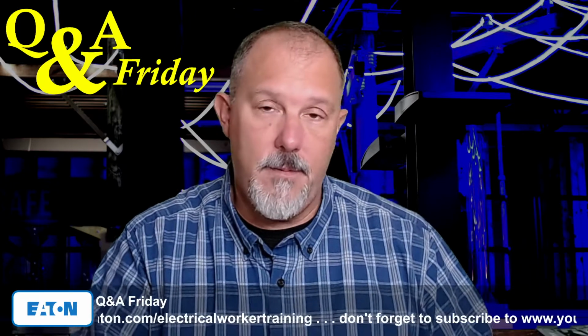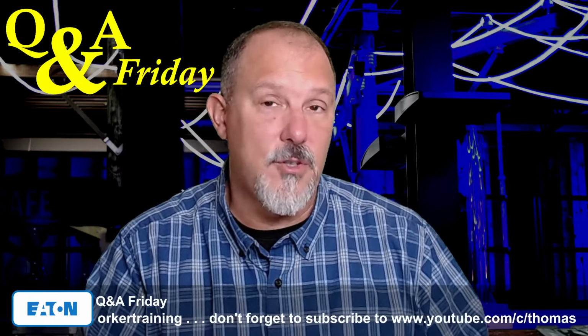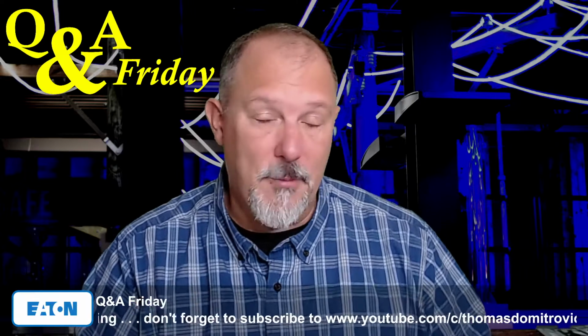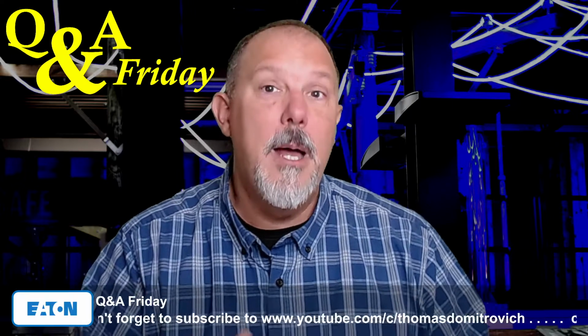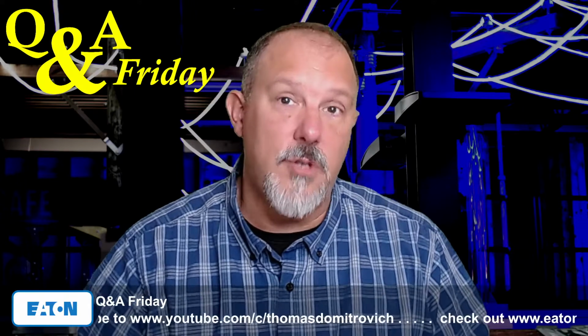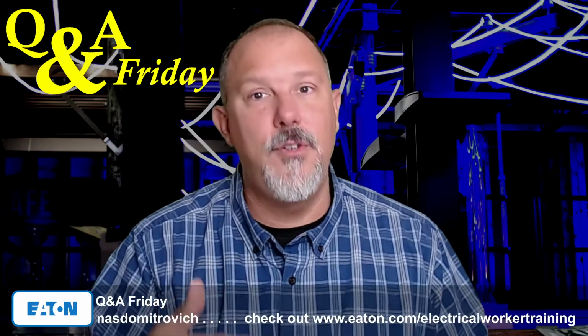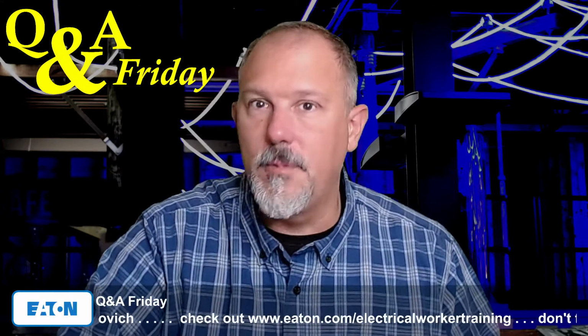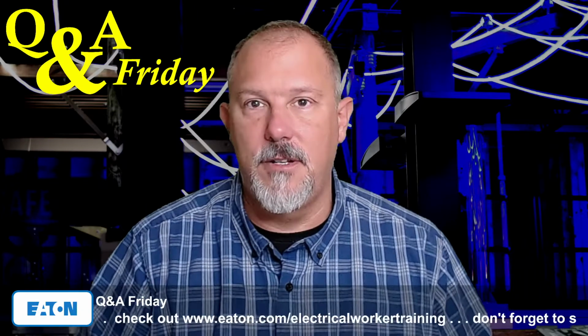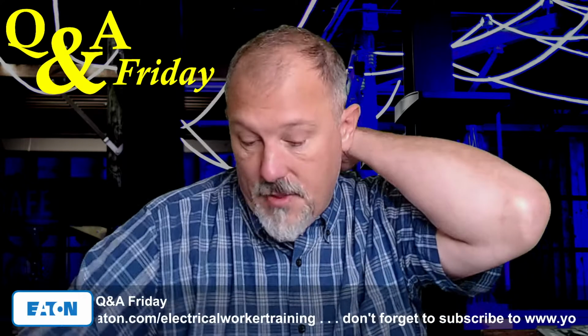But I'm not going to necessarily, because I can still say that the medium voltage equipment is 100% rated and I'm going to follow the exception. But in the next revision of the code, I could delete everything associated with 125% and just make it very streamlined and clear exactly how you size the branch circuits, size your overcurrent protective devices for that protection after you do your load calculations, etc. So that's my thought process on that.